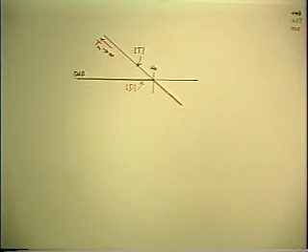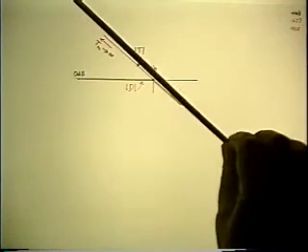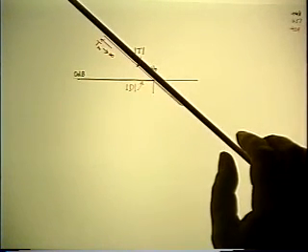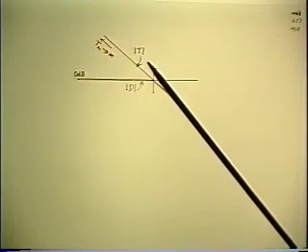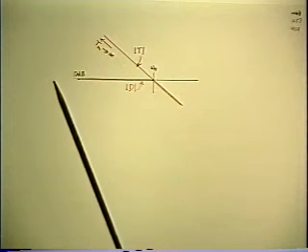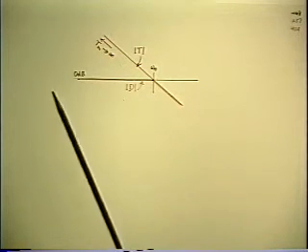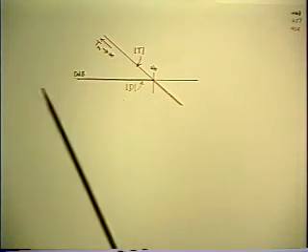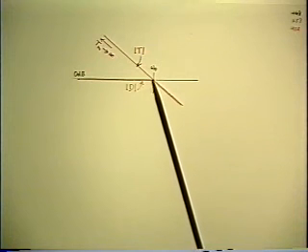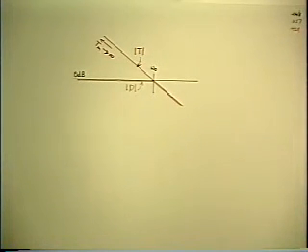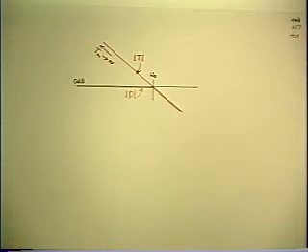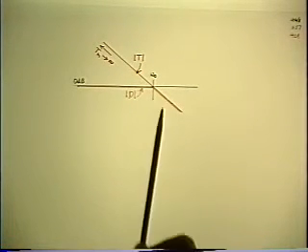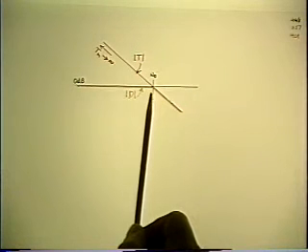So we start with the simplest possible problem, which is a single asymptote for T, and we don't care where it came from at low frequencies. And the corresponding closed loop gain, which is proportional to D, is going to be 0 dB with a pole at omega 0. So we've simplified the basic problem, stripped it down to the only essentials we're interested in, which is what happens to the shape of D near crossover.